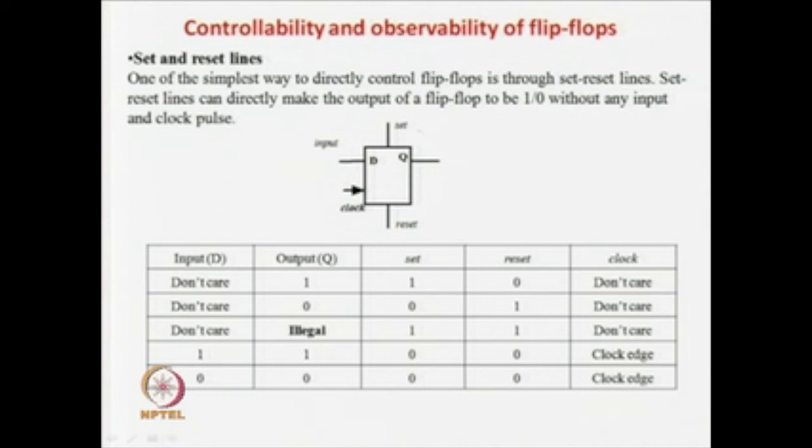So, you have to indirectly or directly, whatever you can say, without using explicit test patterns, get access to these flip flops somehow and control them. Indirectly, if you want to control them, you can apply d-sequence number of test patterns and go for a time frame expansion. But here what we are saying is that this indirect control, we have to do somehow directly. We have to directly somehow access all the flip flops.